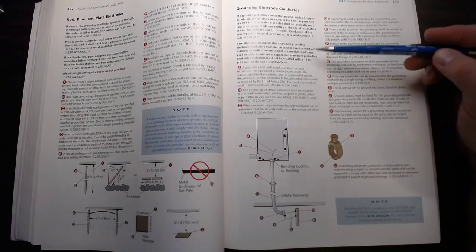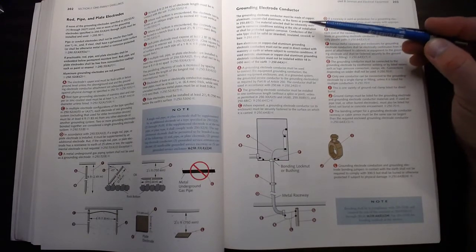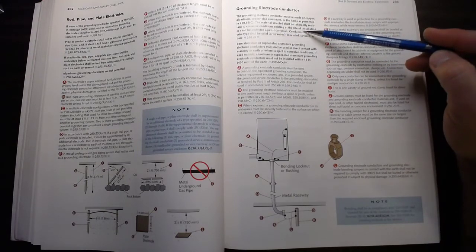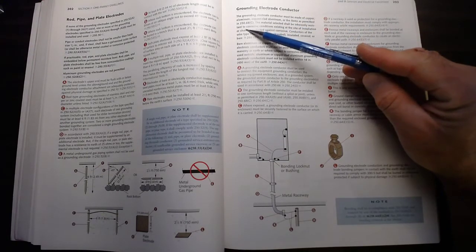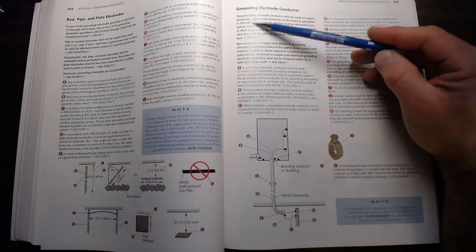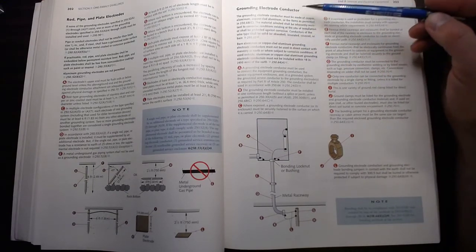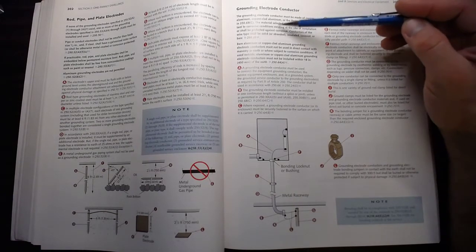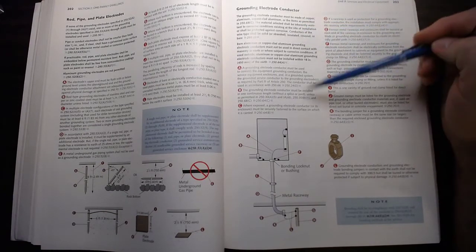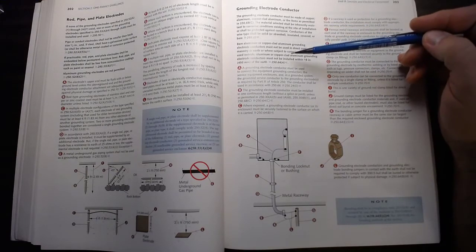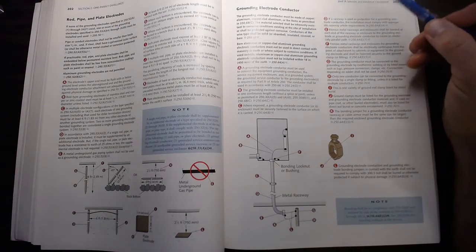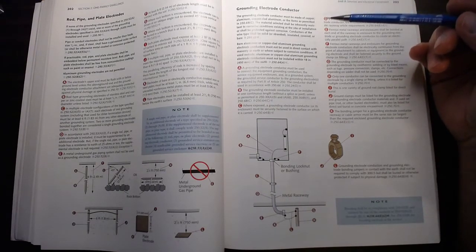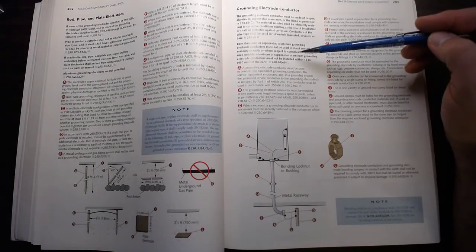The grounding electrode conductor, we need to make sure that it is made of copper, aluminum, or copper-clad aluminum, or other items permitted by 250.68(C). It needs to inhibit corrosion, so it doesn't corrode. I've seen ground rods corroded off in salty areas, where stainless steel should have been installed, and they had no grounding system because that ground rod had corroded off.